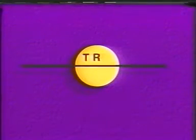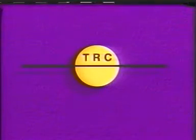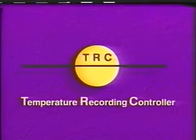The letter identification for an instrument symbol is usually arranged in this order. A circle indicates the instrument. The letter of the variable being controlled appears to the left. If the instrument records or indicates, this is indicated by a middle letter. The letter on the right side tells you the instrument that does the job. The letters in this instrument symbol stand for Temperature Recording Controller.